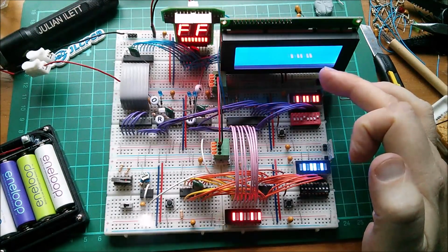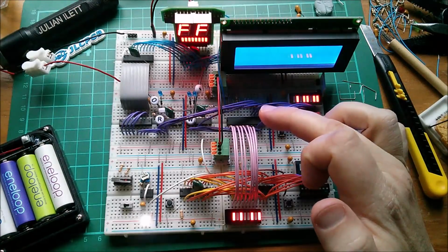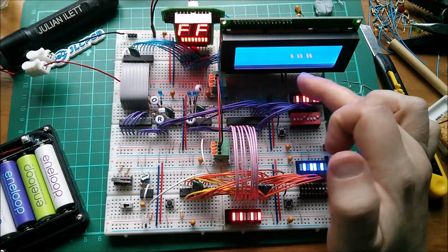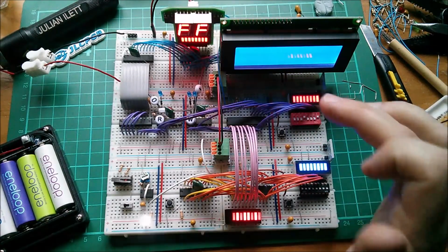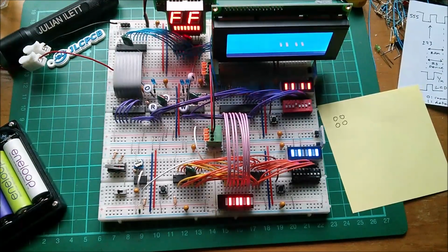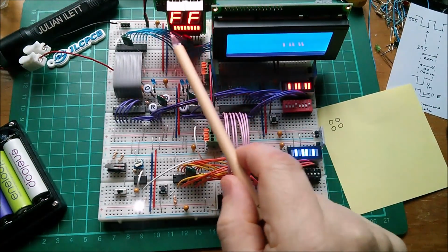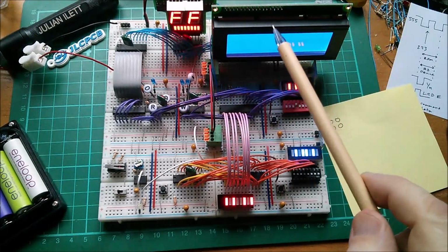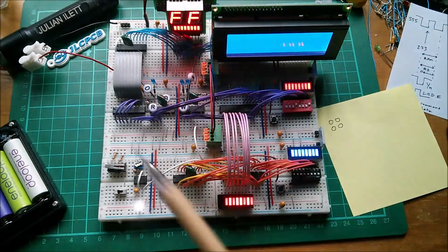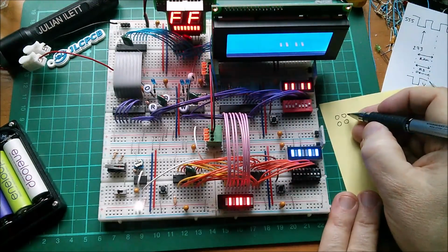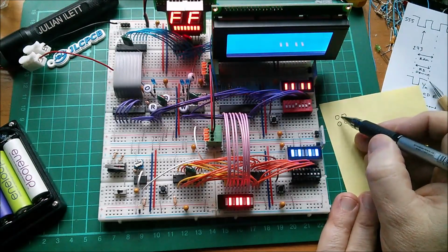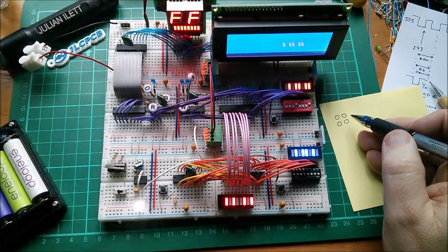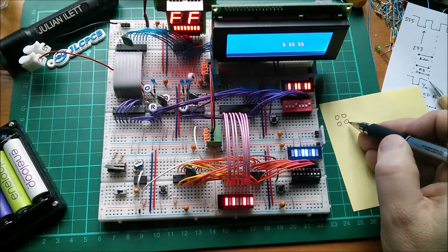But the next thing is to write a couple of instructions into the memory, which puts this into a mode with a blinking cursor so that we can see something. So I'm just going to work out what those are. The first thing I want to do is put 0 in this latch, because the 0 bit here is being used for register select, and that needs to be a 0, and for some reason this has got FF in it. So I think I need 0, 0, 0, 0, and that writes a nibble, a 0 nibble, to the constant generator, the literal generator, and that writes the other nibble.